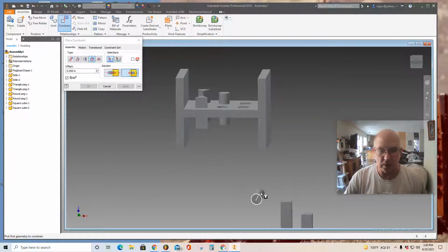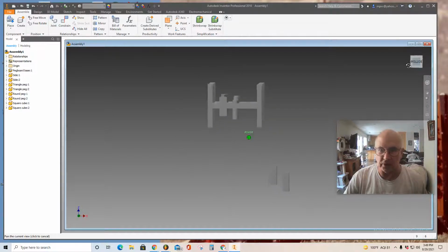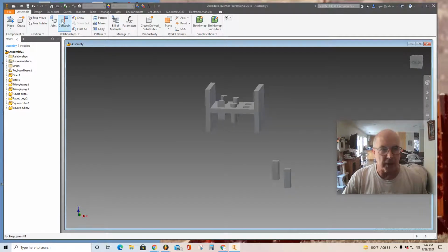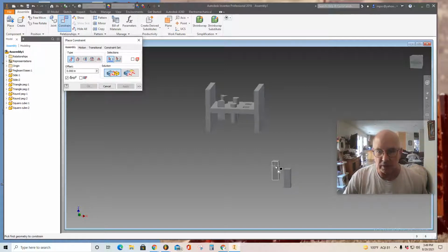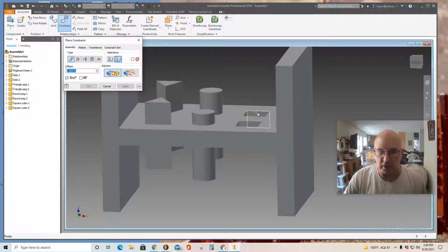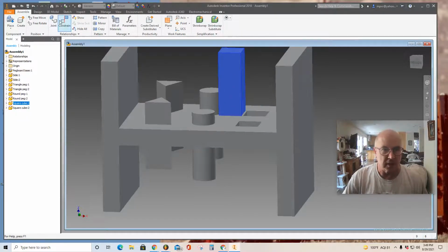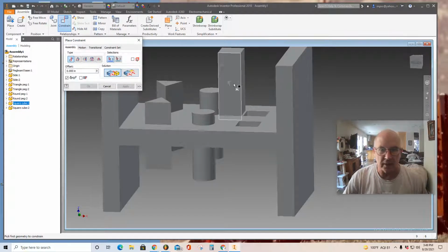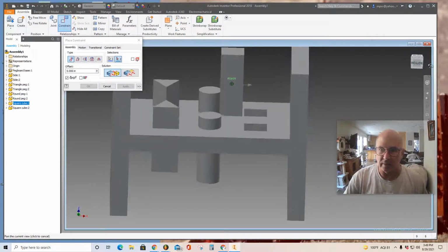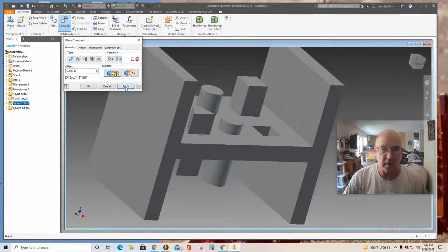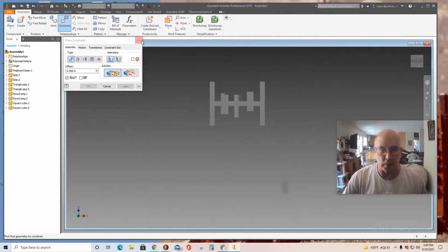So I'm in the insert tool. You find that ring, select here, and then maybe a -0.5. I'm trying to make things aesthetically pleasing. And then finally, go back to the constraint tool, mate. I'm going to select here and any one of these surfaces here. Apply. If you hit escape, you can move this around still. Constrain, mate. I'm going to select here and here. Apply. Now it won't move, but it will move up and down. See?